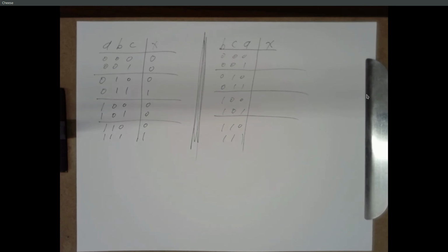Either it's true or it's false. So the OR is always going to be true. So we have A bar ANDed with B, ANDed with something that's always true. Okay. That's just the same as A bar ANDed with B. Right. So you can just do this with 6 and 7.